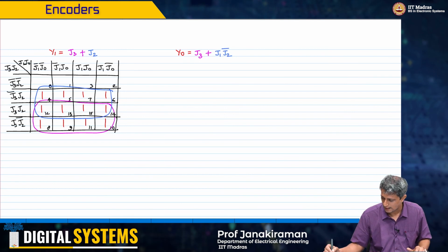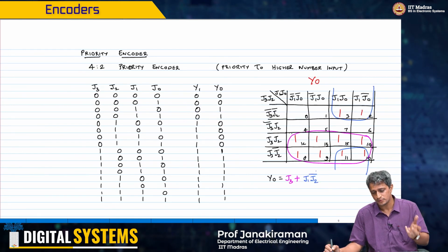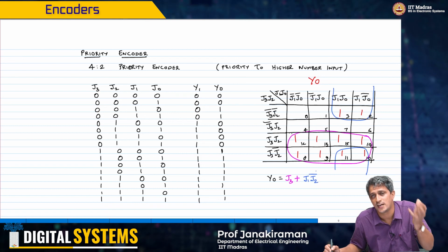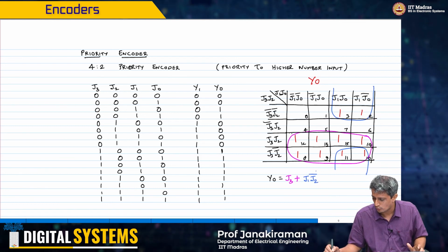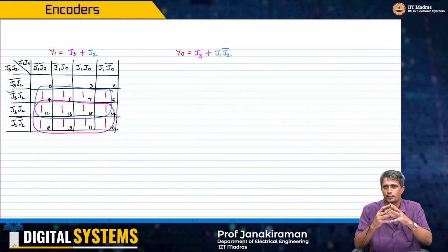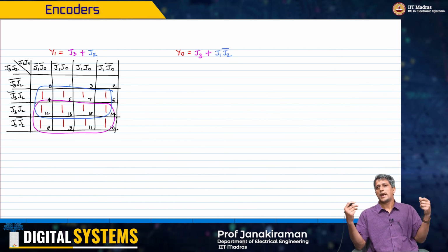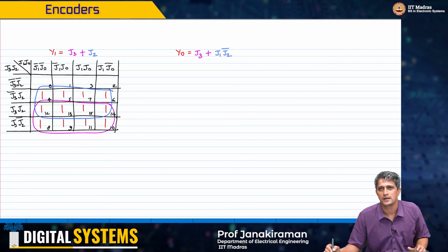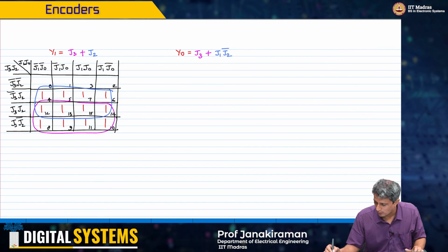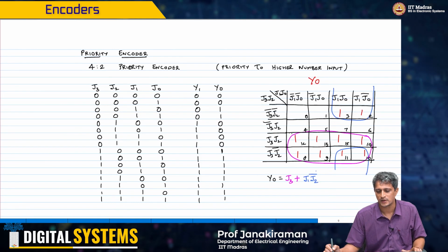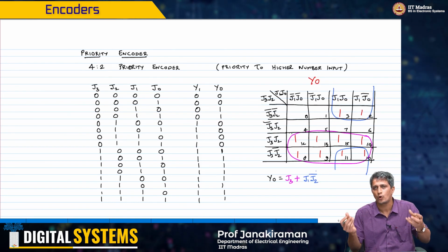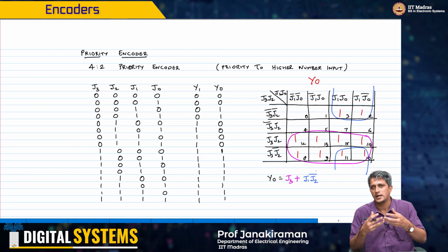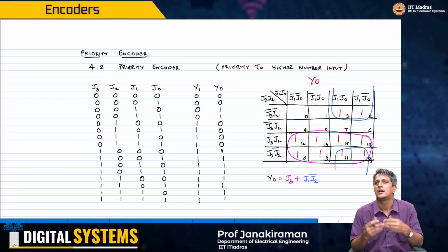Like I mentioned here, this is very advantageous because we are not putting a constraint on the input. The priority encoder takes care of any input combination and ensures that the output is suitably high and produces the necessary output as needed. So with that, I'll wind up this discussion on the general encoder, decoder, multiplexer, demultiplexer that we have done over the last few lectures. Thank you.